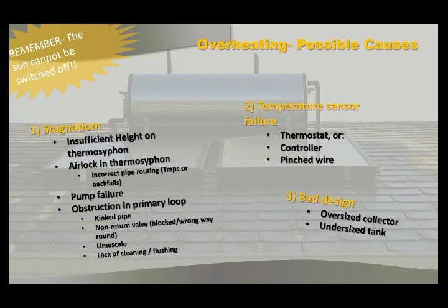And you know, you might install a solar system in May and only come across the stagnation issues because of the temperatures in September or August. It's 3 or 4 months down the line, and so this is the danger. Then as summer hits, now you've got serious issues, and that thing starts to overheat, and all kinds of things can happen. In a pumped system, a split system, you can have pump failures.